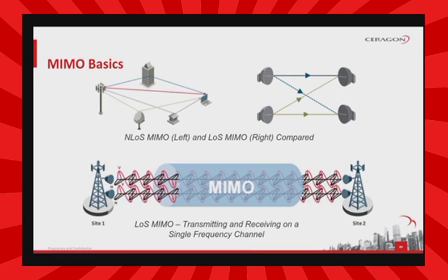Line-of-sight MIMO achieves spatial multiplexing by creating an artificial phase correlation with a deliberate, planned, constant distance between the antennas at each end of the radio link. At each site in a line-of-sight MIMO configuration, data transmitted over the radio link is split into 2-bit streams in 2x2 MIMO, or 4-bit streams in 4x4 MIMO. These bit streams are transmitted via 2 antennas. In 2x2 MIMO, the antennas use a single polarization, while in 4x4 MIMO, each antenna uses dual polarization. The constant phase difference caused by the antenna separation enables the receiver to distinguish between the streams and allows for the capacity increase.